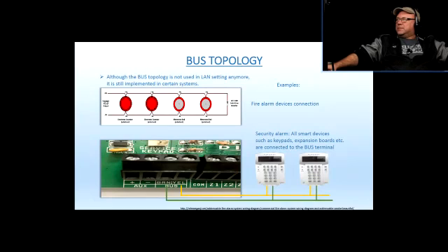So it is going to trigger something that's called a trouble condition, which means it's not a fire condition, it's a trouble condition, which means that the sensing circuitry is in trouble. So if there would be a fire, not necessarily the fire would be recognized by the system. That manifests as some annoying beeps in the fire panel, repetitive annoying buzzing beeps, and whoever is in the building is going to be annoyed by that.